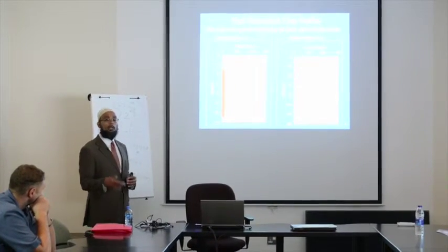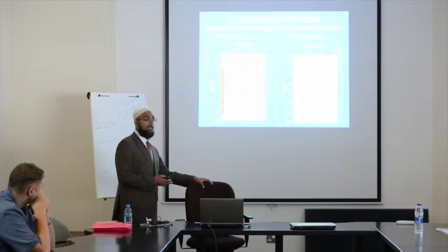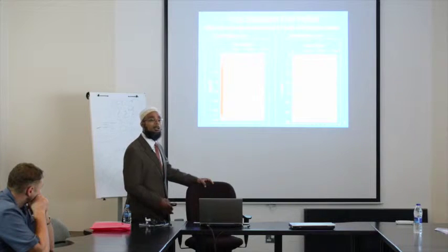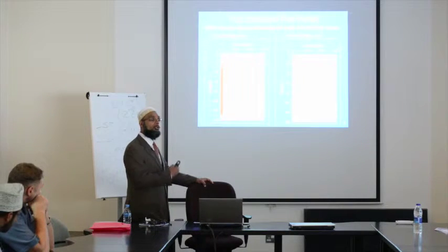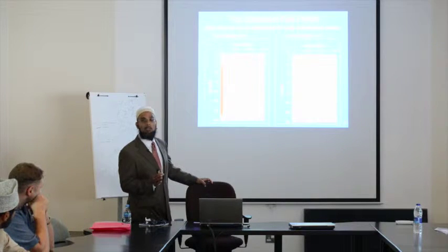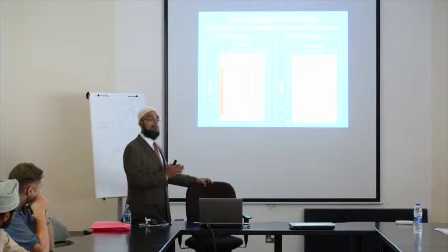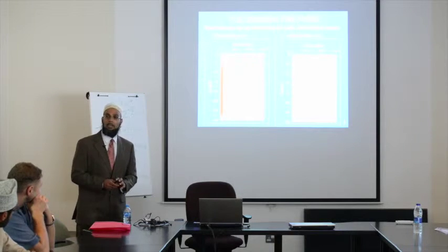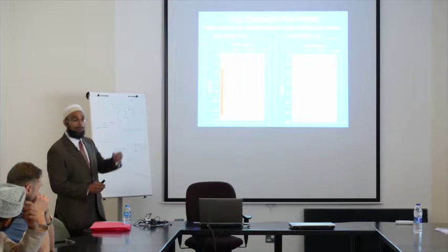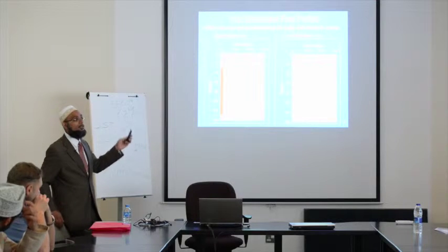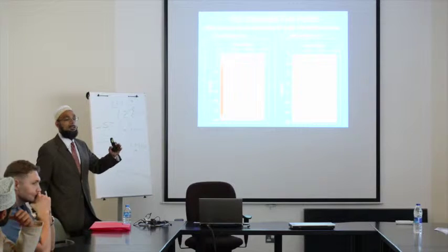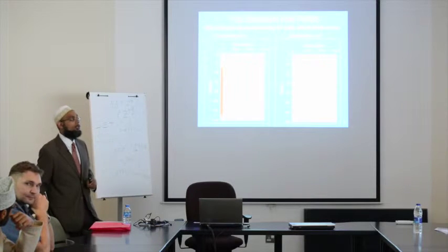So what will happen if you're water flooding? You may have issues like scale formation. If the pressure depletes, you may have asphaltene precipitating out. So a lot of issues would arise because the carbonate stimulation treatment was not done properly in the first place. And if we are only looking at the total production rate at the well surface, right, they will look the same. Both have the same skin. But only when we do a flow profile do we see the difference between the two treatments.